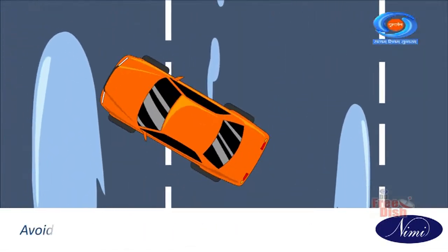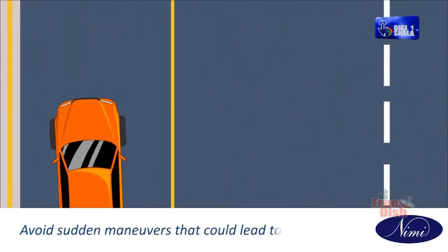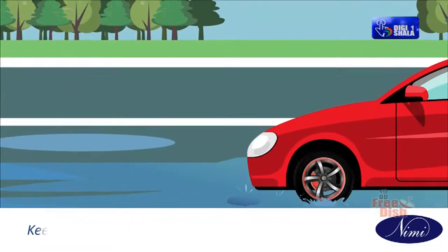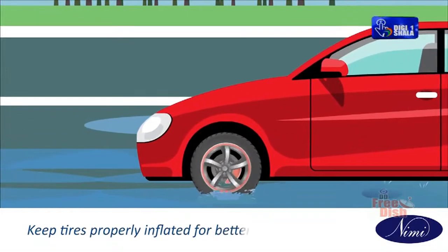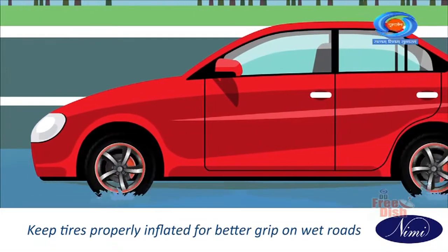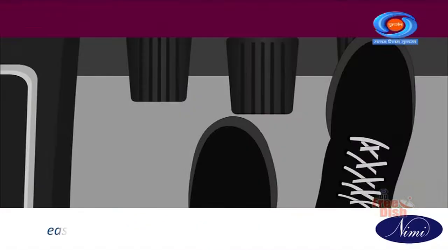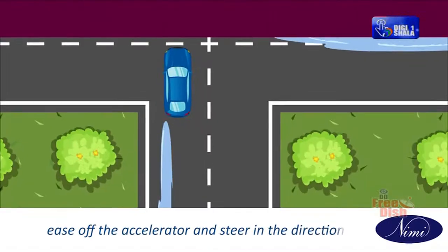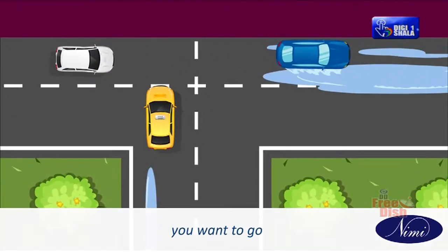Avoid sudden maneuvers that could lead to loss of control. Keep tires properly inflated for better grip on wet roads. If hydroplaning occurs, ease off the accelerator and steer in the direction you want to go.